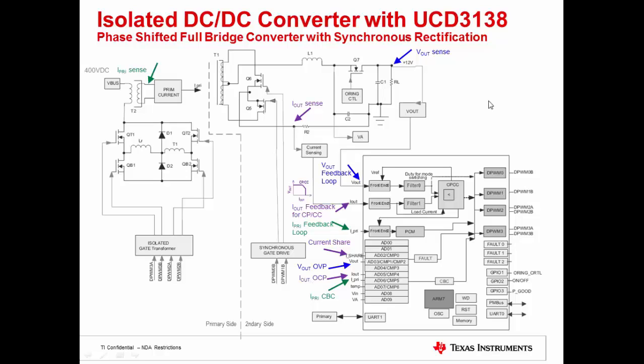Having made the decision on what control signals will be presented to what hardware blocks, the exercise of programming the digital controller to control this power supply is simply a matter of following the recipe which configures the appropriate registers for delivering the appropriate functions with the controller. In terms of the output, the DPWM modules 2 and 3 are used to control the primary side MOSFETs, while the DPWM modules 0 and 1 are used to control the synchronous rectification MOSFETs on the secondary side.